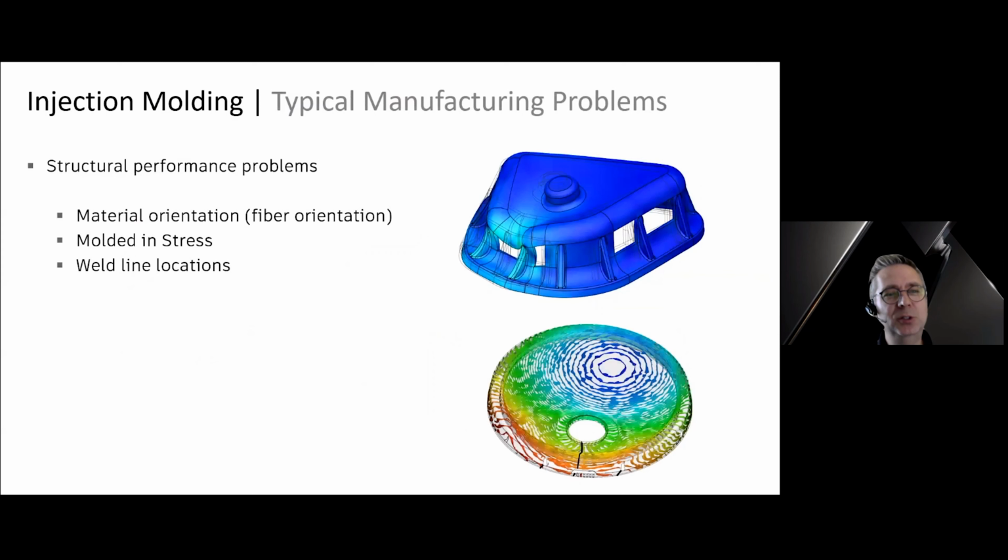The last thing I'll mention is that some of those issues I've already talked about, as well as some other things, have the potential to cause structural performance problems, where the part just doesn't perform as it's intended to. Sometimes that's from things like a weld line, where the flow front comes together as it flows. Sometimes those end up being very weak.